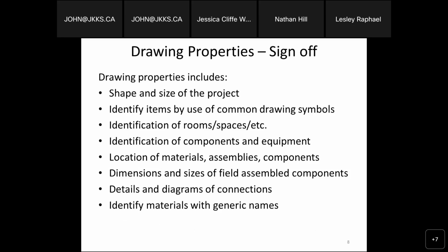So, drawing properties and thinking about sign-offs. When we talk about drawing properties and sign-offs, I want you to think about how all the drawing properties must be reviewed and approved prior to the official release. Certainly this puts a lot of responsibility on the backs, or into the hands, of the architect and or the engineer. Otherwise, they most often would be considered in draft form only, as I indicated earlier, with the word draft stamped usually across the drawings.